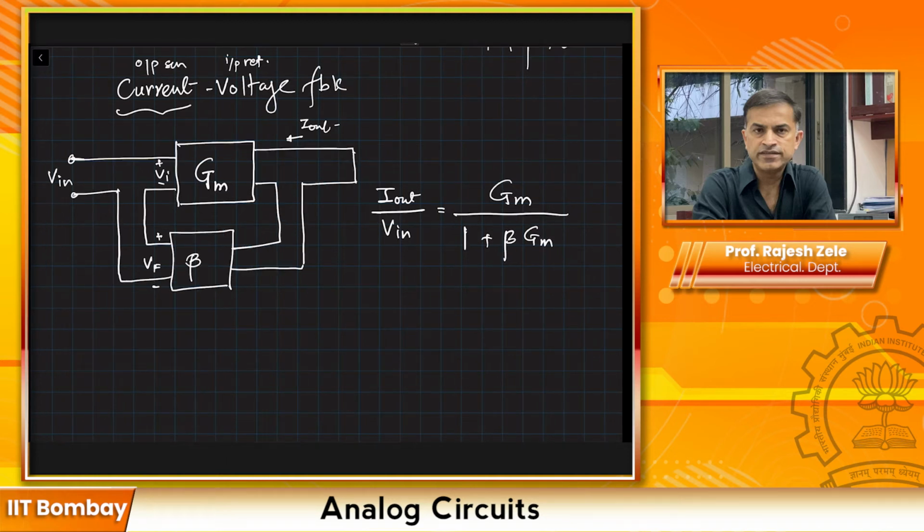So in this case, let's use our intuition that I taught you a few minutes ago. What is going on at the output? At the output, as it looks like, things are in series. So whenever things are in series, what happens to our output impedance? It should go up. Similarly, at the input, also we see things are in series. There are two series blocks connected. So input impedance will also go up. And that's exactly what happens.